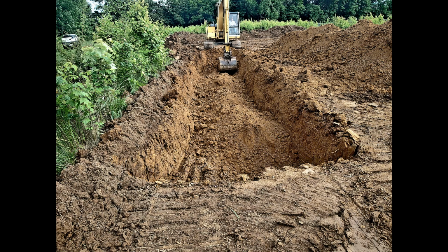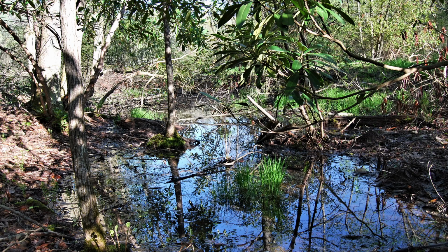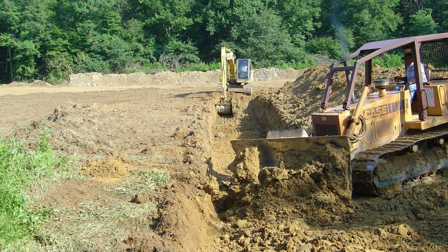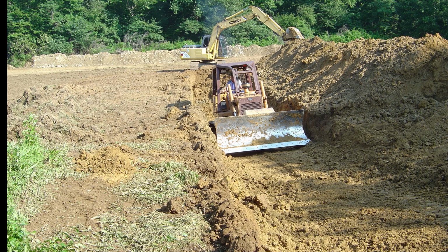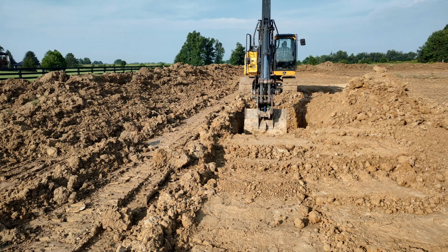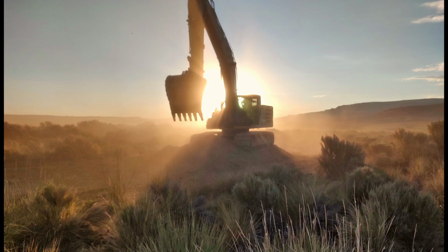Building a groundwater dam is the most effective and the lowest cost way to restore or create a wetland of any type and of any size. Some people have other names for groundwater dams. They call them core trenches, keyways, cutoff channels, but no matter what you call them, they all work the same to ensure the wetland that you build will hold water as planned. The excavator is the primary piece of heavy equipment that one uses to build a groundwater dam.